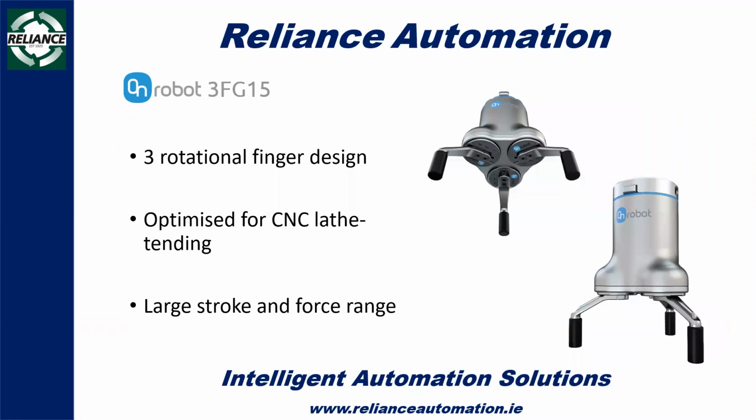One of the newest ones that they've come up with is the 3FG15, and it's very literal, the naming. It's a 3-finger, 15-kilo payload. What's great about this design is it utilizes rotational force on the grippers as opposed to your standard linear actuation stroke. And what makes this great is the likes of CNC machining of cylindrical billets. They can grab hold of them and centralize them within the gripper, moving them onto the machine afterwards.